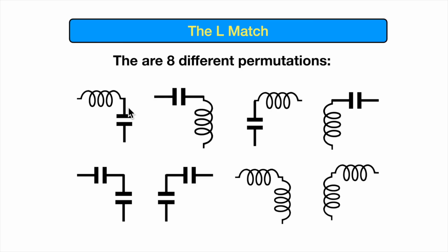Okay? So the shunt end, the parallel component, needs to be on the side, there's two ends here, the front and the back. So on this back end of the inductor here, this needs to be the element with the largest impedance, and this is the smaller impedance.